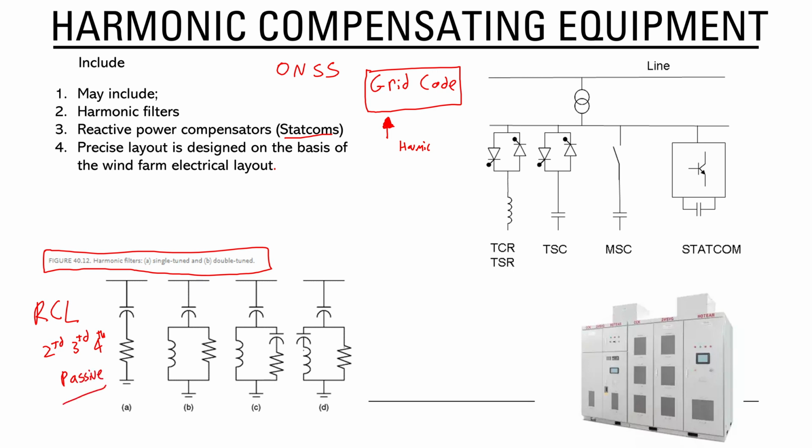They don't generally need a lot of input from us, but because of the capacitors they are very dangerous and are generally put in a special room with controlled access, because those capacitors can have ridiculously high voltages and stored energy.